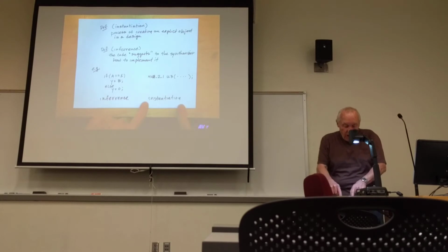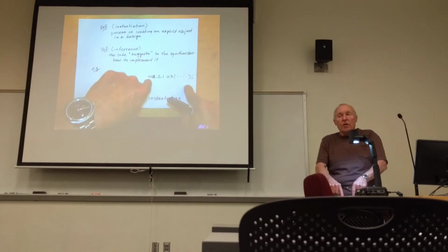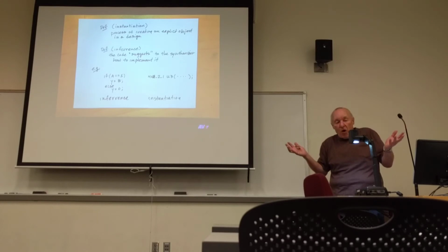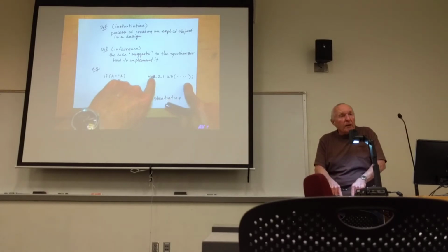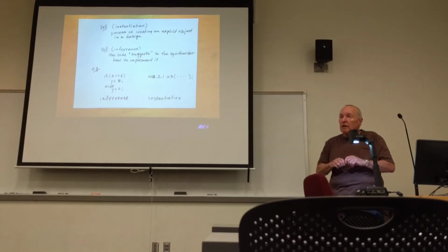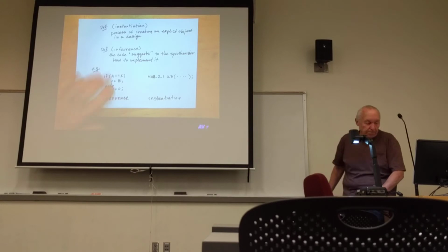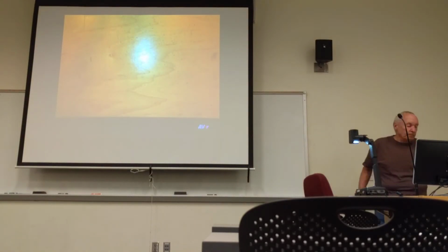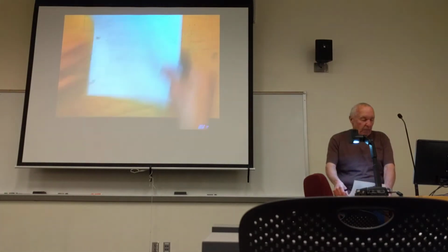So in an instantiation, you tell the synthesizer, the synthesizer's not free to do whatever it wants to, you've told it exactly what you wanted. Inference, you suggest by the way you've written your code how the synthesizer might implement it, and the synthesizer will figure out the final implementation. Okay? So that's the difference between instantiation and inference. So back to my DesignWare component.